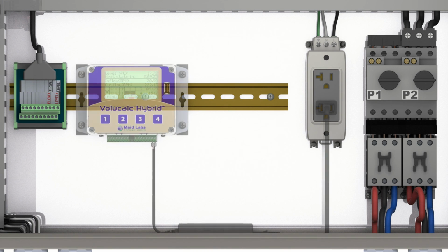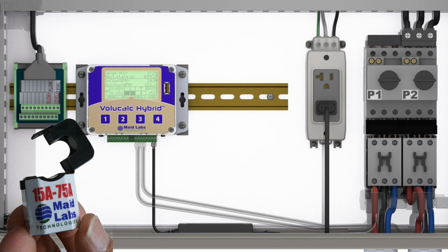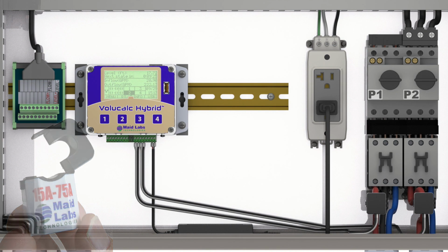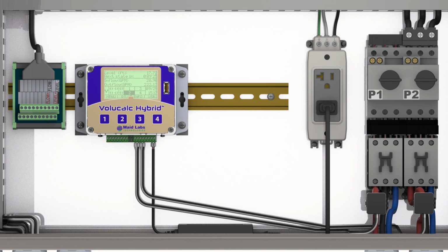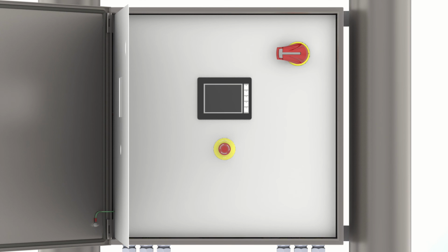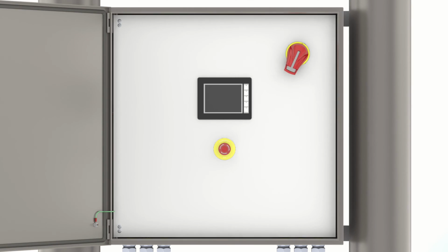In this case, what I'm showing right now is that to install this device, it's just a matter of putting 1 current clamp per pump. You just connect the device to a wall outlet, and the instrument is connected. And that's all there is. After that, you need to set it up. If you have a level sensor, we suggest to use a current isolator. And so you piggyback on that level sensor, and you have quite a lot of information out of this.